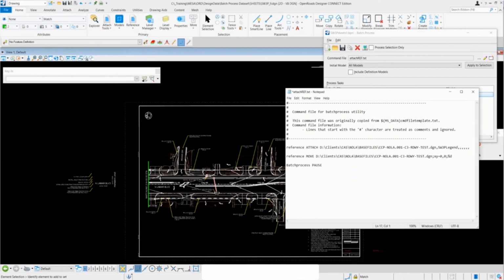That's kind of just a check for myself. Okay, the next key-in that we used was the reference rotate. So I'll type in reference rotate, and then I use the points method, so I'll type in point. After that, I'll type in the reference that I want to rotate, which is this one. And if you recall, the two data points for that one were also user input.